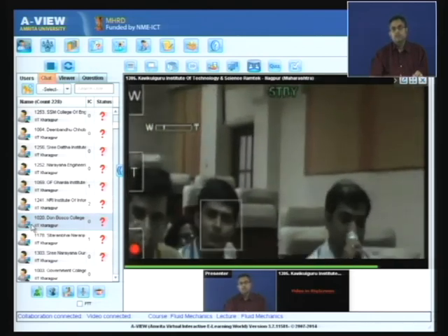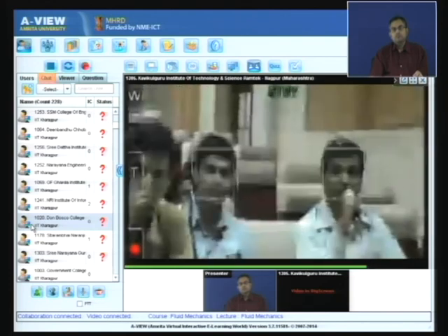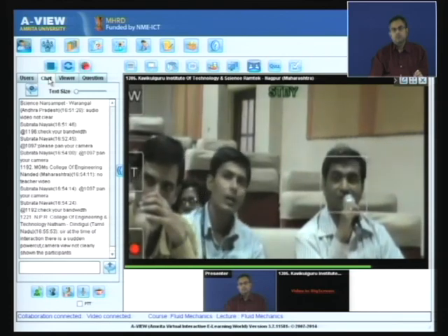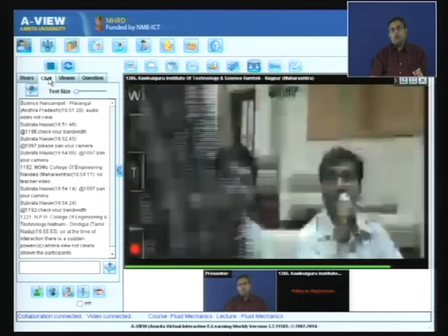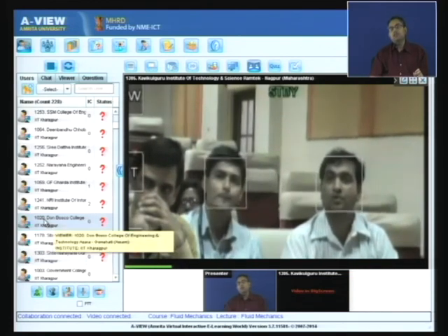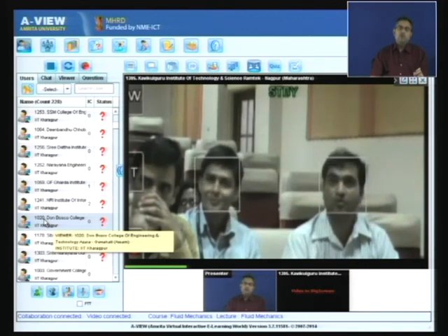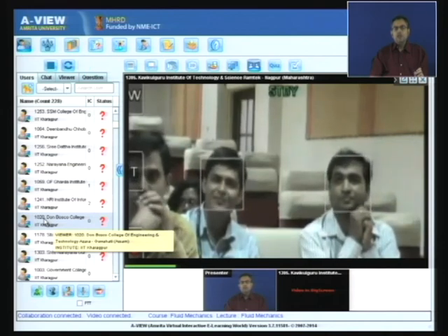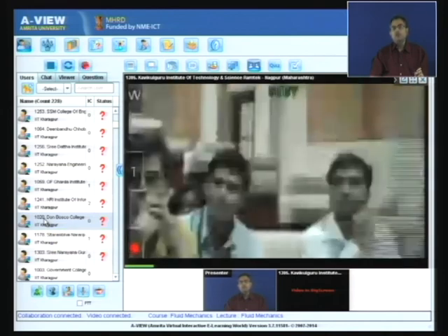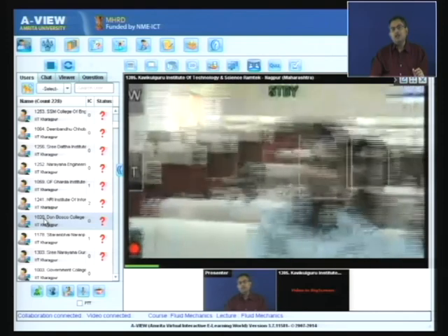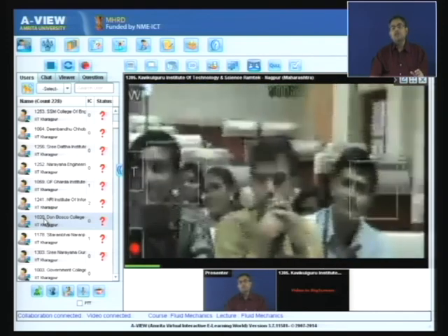Sir, my question is why we are studying the boundary layer concept. Please explain it with certain practical examples. Okay. Let us say that you want to study flow past an aircraft or flow past the body of a ship. Depending on the relative velocity between the fluid and the solid, there will be a Reynolds number, and based on the Reynolds number you can define a thickness within which viscous effects are felt.